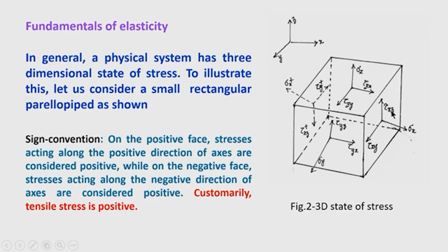So, therefore, the second subscript is given as z. Similarly, here you can see tau xy, x denotes the normal to the face and y denotes the direction in which the stress acts. In this face, we see that the normal stress is sigma y, and the shear stresses are tau yz and tau yx. Okay. The first subscript you can see here is y, that clearly indicates that y is the normal to this face.